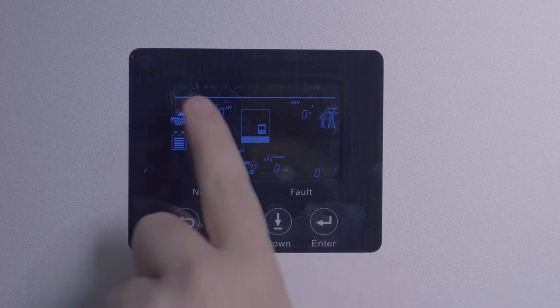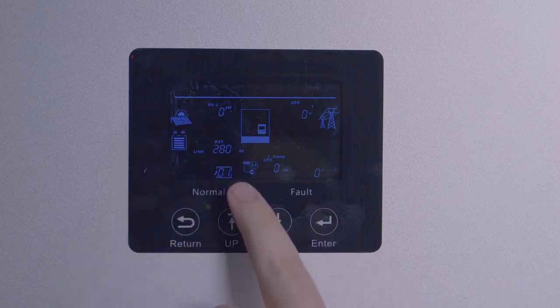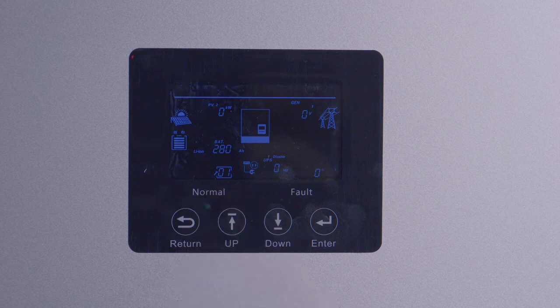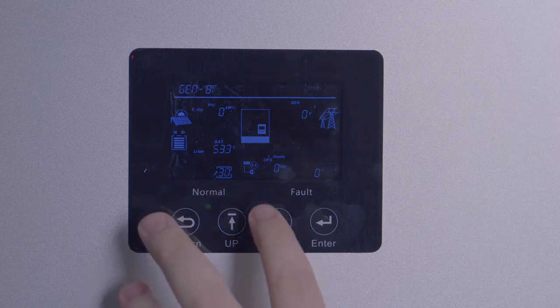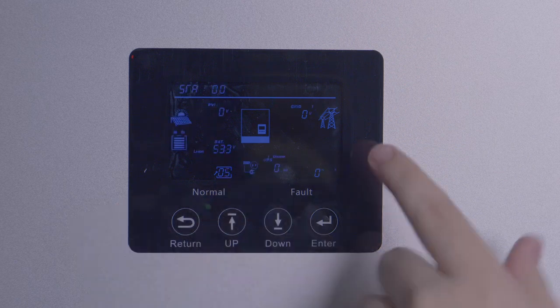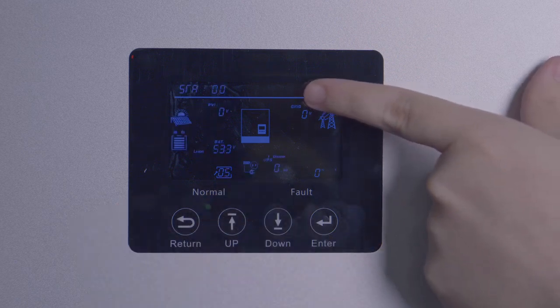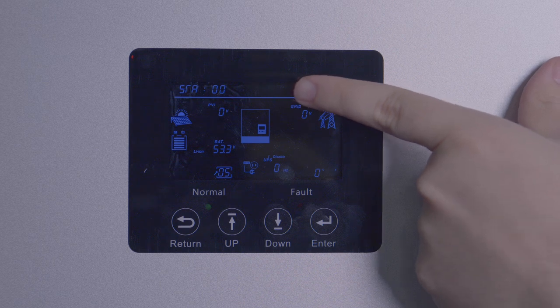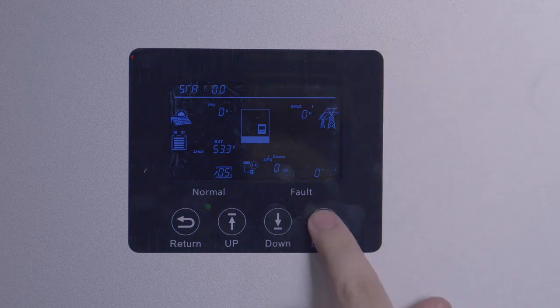You should hear a double beep when you let go and the screen will be flashing. Since we're commissioning on the physical interface, we're going to turn off the buzzer during the process for my sanity's sake, and likely yours as well. The first setting to go to is setting 5. Press enter once on the setting and down to change to disable, then press enter again.